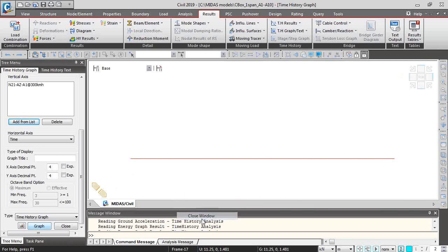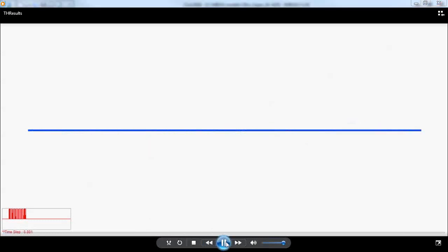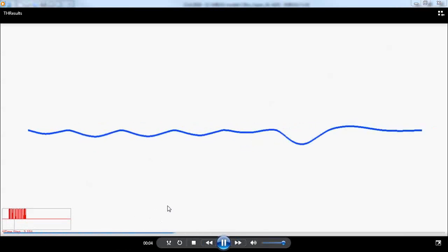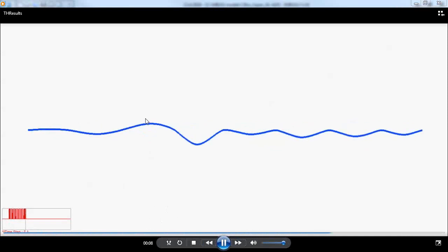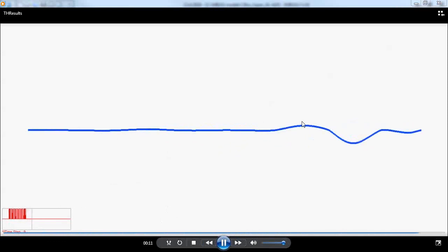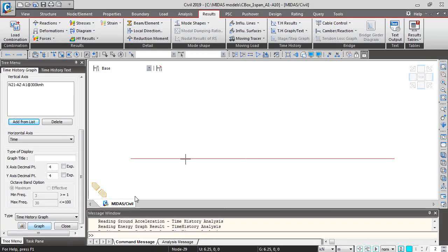Right. Another thing that you can do is extract results as a video. It also helps you to see how your bridge behaves under the train. This is not the same load, the study case. This is a multi-span bridge, but I thought it was interesting to see how the load moves along the bridge, and then you can see all the flexions. It's useful as well to see if you have any spurious results and there is something wrong. You will spot it very quickly in the video.